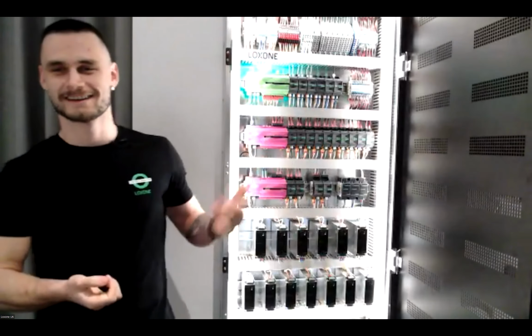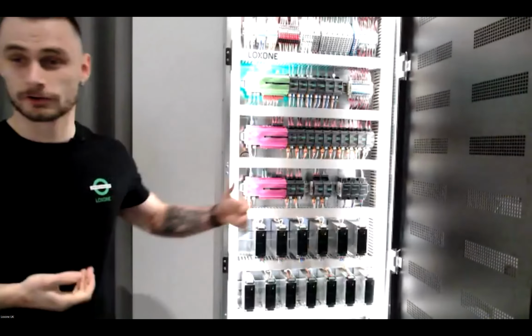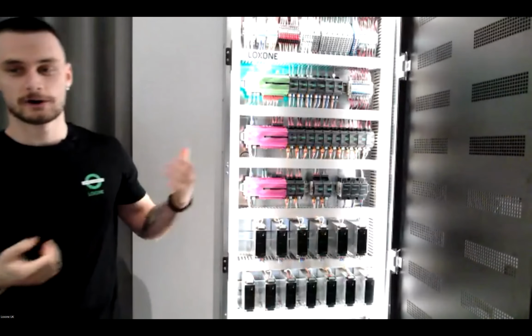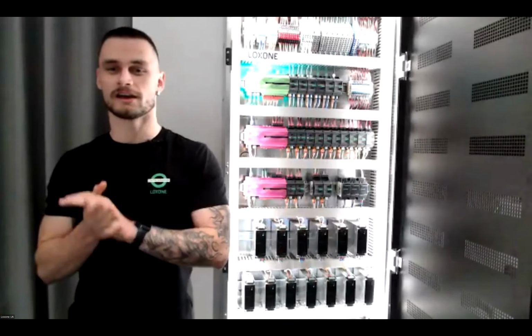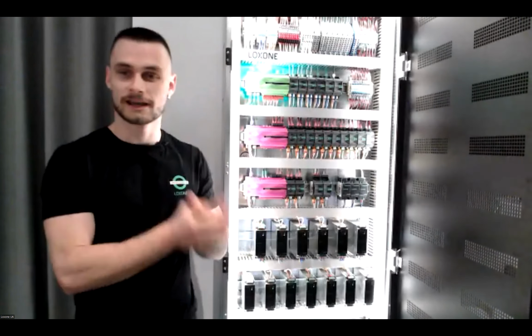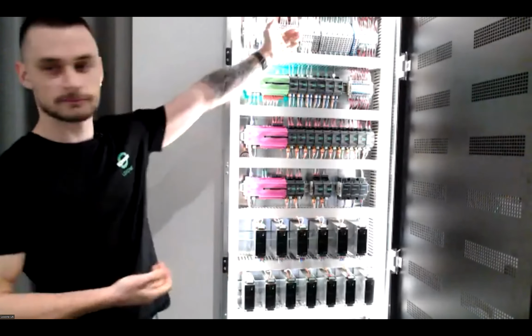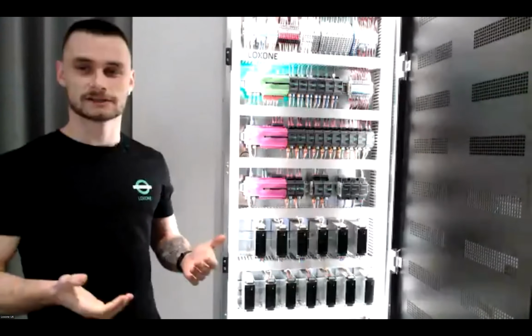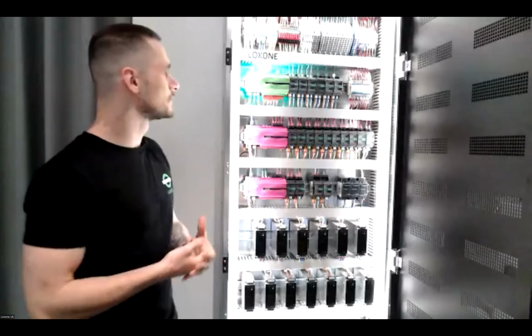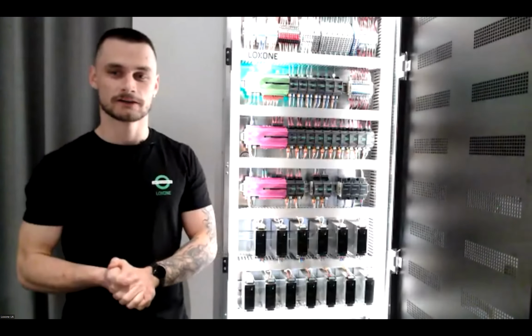Today's topic is obviously going to be panel layouts, best practices. We're going to talk about power supply, how many you need, why you need that many, how to spec the number of power supplies that you need, and how many amps are actually going into the project. We're going to look at the terminal blocks because this is a very frequently asked question, and we want to make sure that we have the best setup or close to the best setup we have.